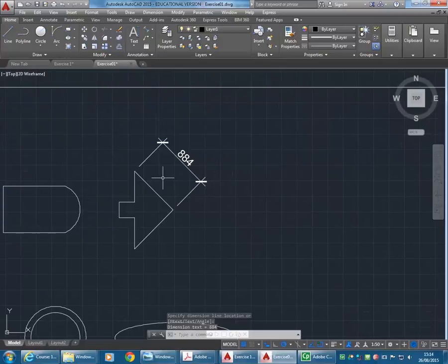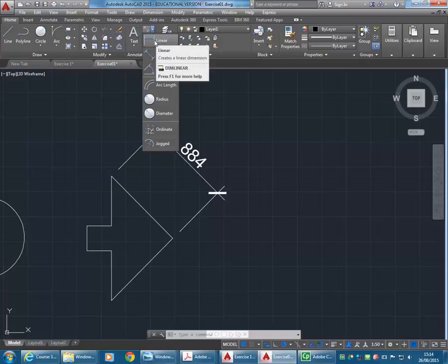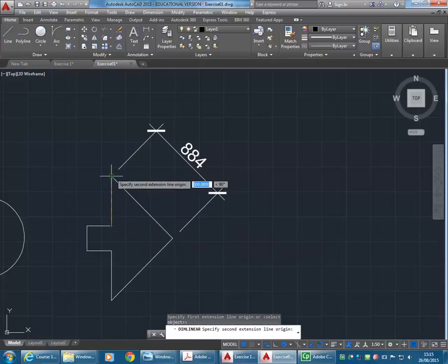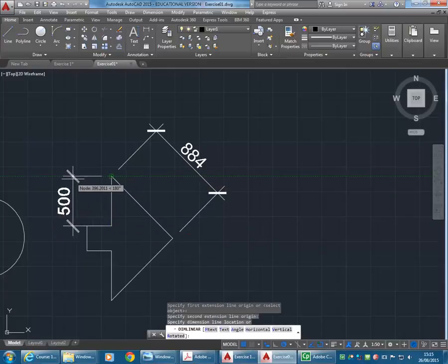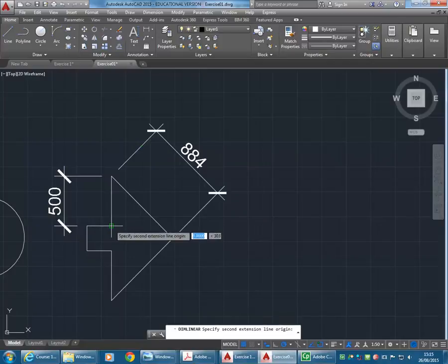At first, that's something you will probably attempt to do, because you might think, well, I've drawn a line that's at a different angle, and I want to know how long it is. But what you find, people with a bit of experience working on these drawings will very rarely do that. Normally, a better way to dimension that is just with linear. So linear won't give you that diagonal measurement. Linear instead only gives vertical, or, so I'll just bring this back, vertical or horizontal measurements.